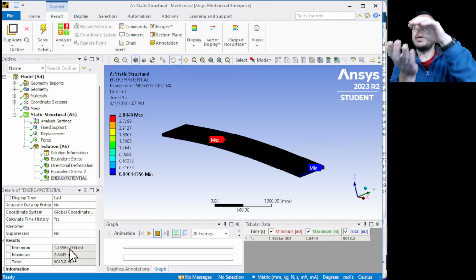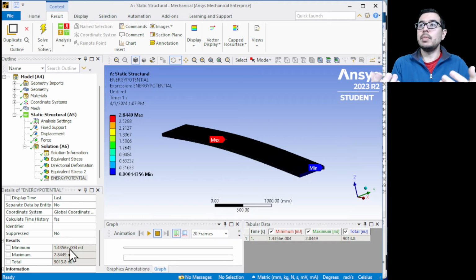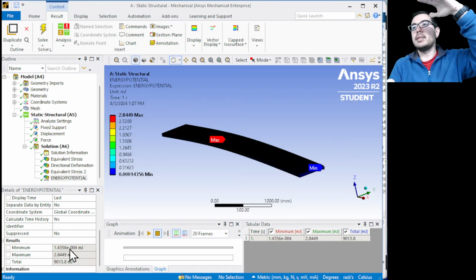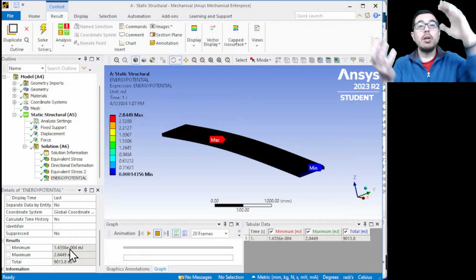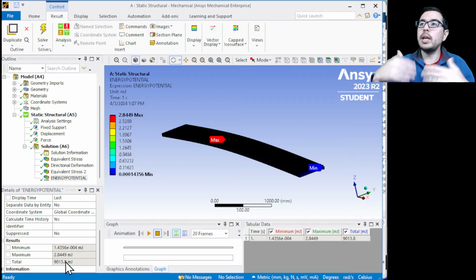they get sprung up. But at that point where the board bottoms out, the potential energy is at a maximum, right? The kinetic energy is at a minimum. Where is all that potential energy? Well, it's stored in the beam. All right, that potential energy is stored in the beam. You can also say, well, you also have a change in potential energy because the diver was higher and they're lower, but now it's all in the beam. All right, and that is what we consider to be the strain energy. All right, and we can think of all that strain energy in the structure itself.